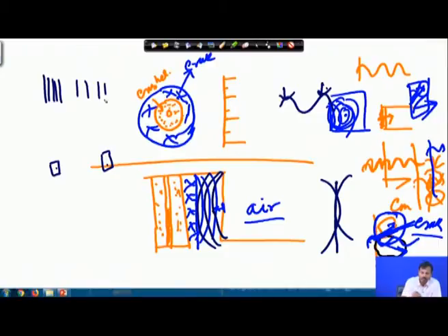So, whenever the wave is going in this direction, there is compression and dilation, and similarly when it is reflecting back. This is the compressive wave, and the reflected one you can consider a tensile wave. So, in compression and dilation, this is in this direction, while on returning it is in this direction. That means this particular element is under stress because of the front wave in this direction and because of the reflected wave in this direction.